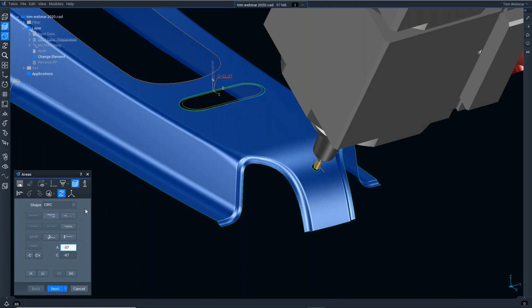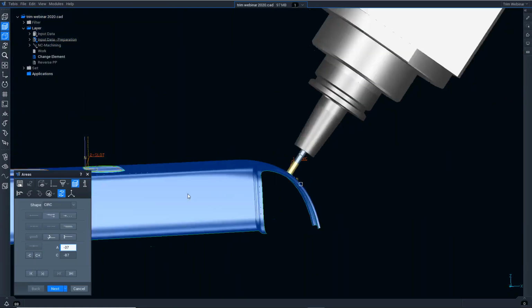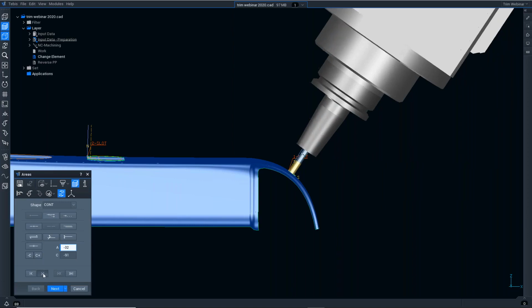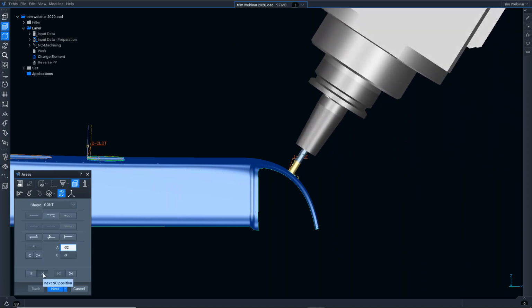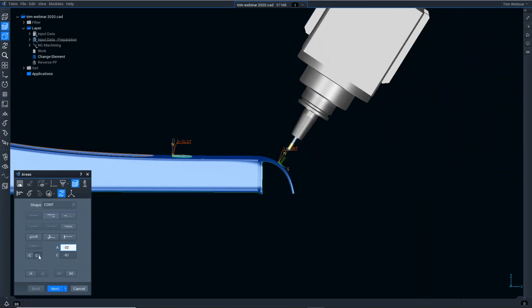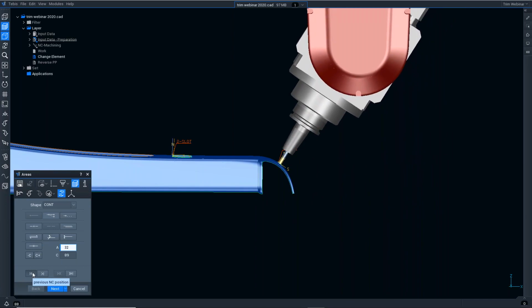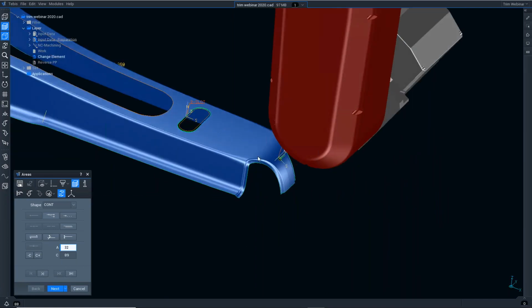So quite simply what this means is, if we take a look at this circle, now if we were to machine this as a plane contour, what we get is a full 5 axis of movement. So we can see the head tipping down and rotating to cope with the angular change around the radius of the component.